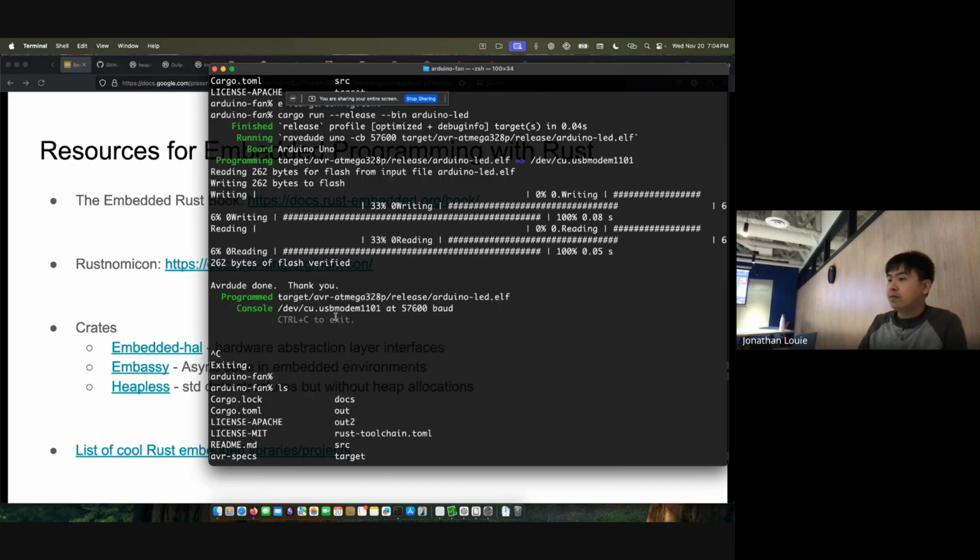And that's kind of your printf style debugging, which as unfortunate as it is, might be what you're stuck with, because some of the others, like the programmers, can be very expensive. JTAG is slow, depending on the exact features of your device. Like it may be very slow to use those types of things. So hooking up to like an I2C device might be the fastest iteration time. Did you encounter that type of problem when you got this one?